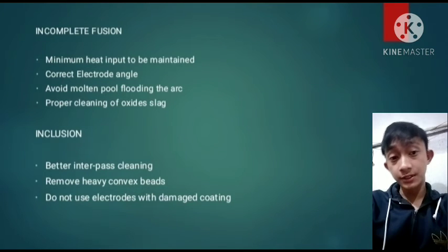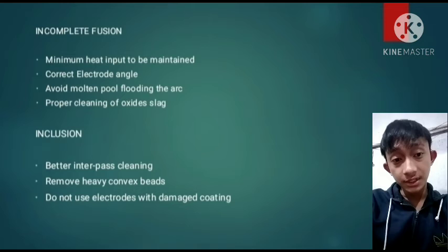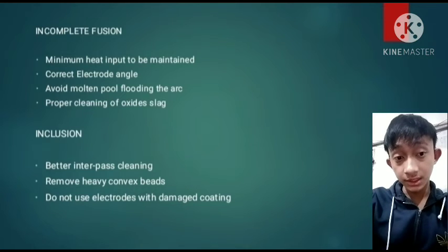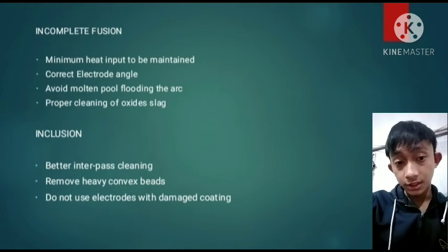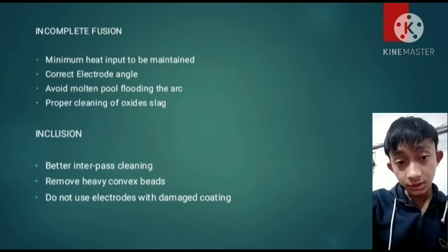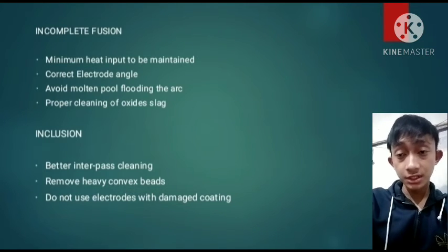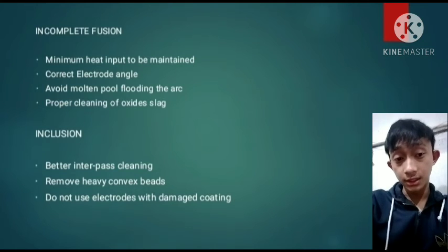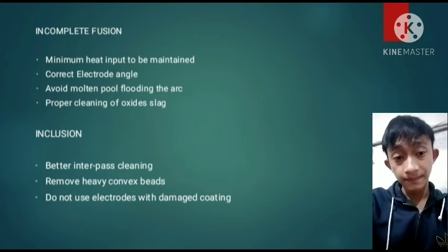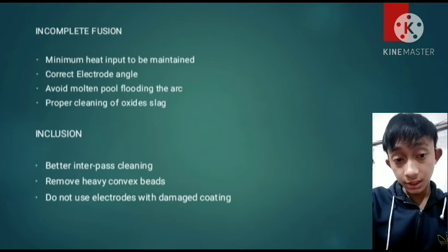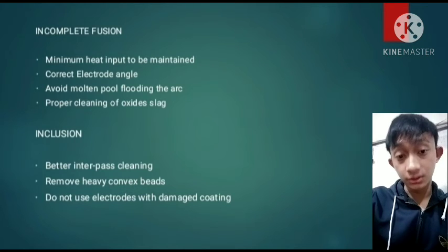Incomplete fusion. Therefore, first, minimum heat input to be maintained, correct electrode angle, avoid molten pool including the arc, proper cleaning of oxidized slag. And then inclusion: better interpass cleaning. Next, remove heavy convex beads. Do not use electrodes with damaged coating.